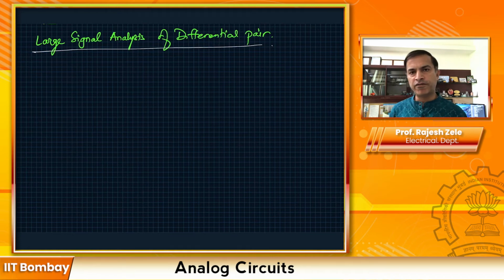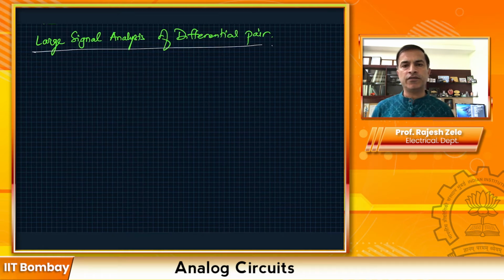In the differential amplifier case, we initially looked at the motivation for the differential amplifier, and then followed up with a simple change: by adding just a current source at the bottom of two common emitter amplifiers, you can achieve how much impact it can make on just amplifying the difference and removing the common mode signal. We talked about that.